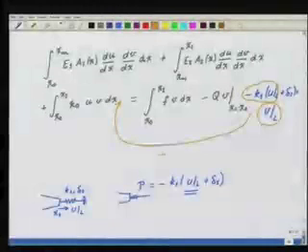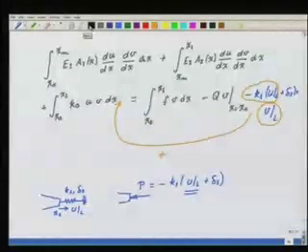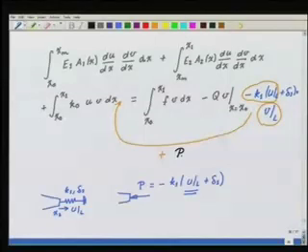So let us now see if this is my weak formulation. The weak formulation could also be derived using the variational principle. Something else is missing here: we have not added the part due to the point load at point x0. So V at xp. This part has to be added to the load vector side.